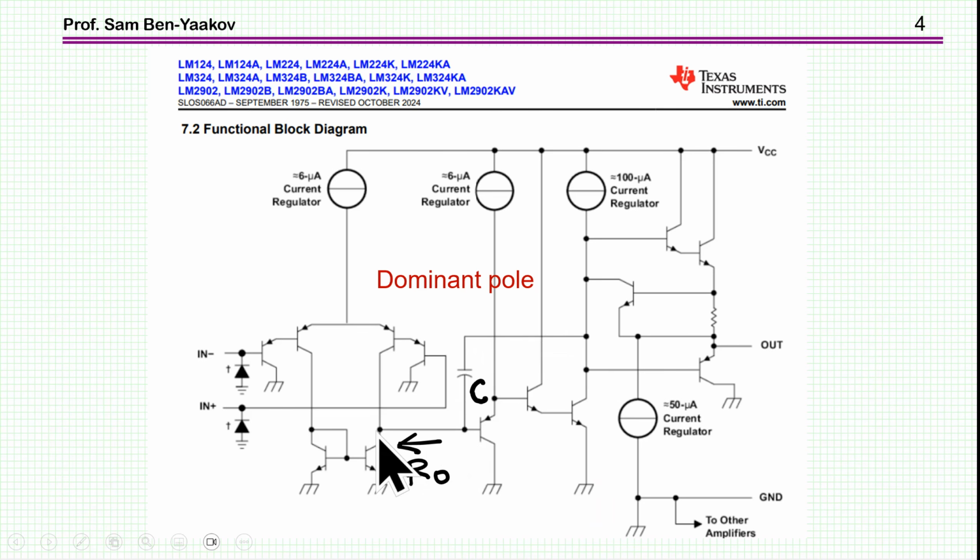It is fed by this differential amplifier at the collector, so the impedance is high. By this we are generating a low-pass filter, or you might say a pole at low frequency, the so-called dominant pole, which helps to stabilize the amplifier for any given load. So this has been used beneficially, using this Miller effect.